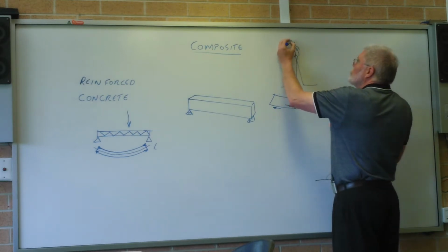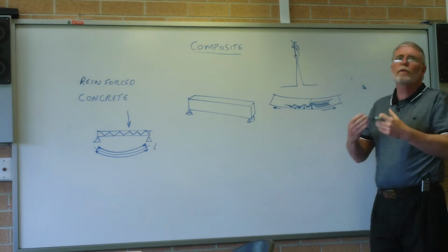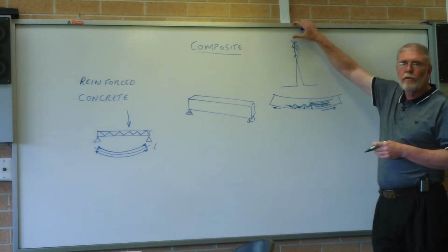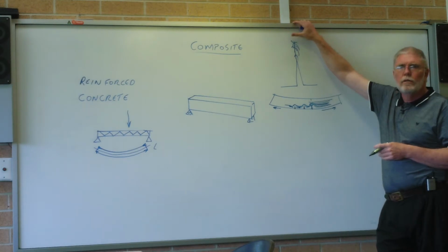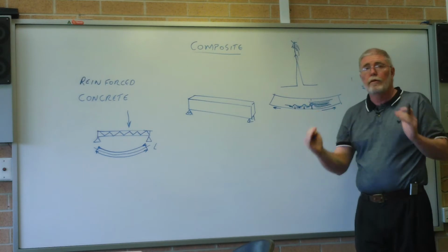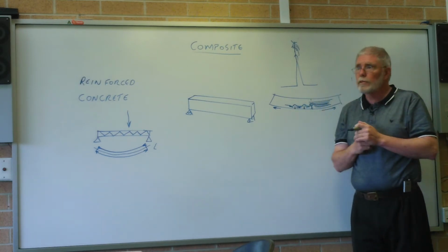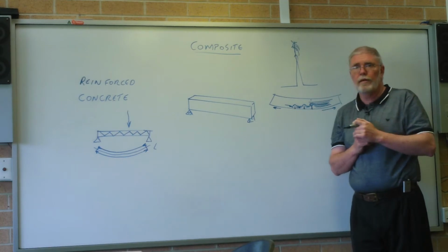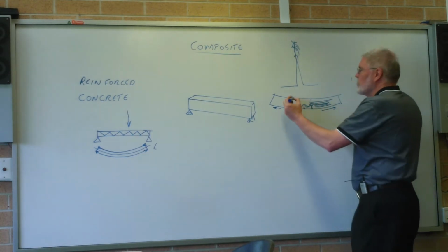So eventually you reach a point where you are overloading the material and what's left in thickness above can't handle the load. It fails. It fails in tension because the cracks open up, forcing the load to the tops of the cracks and making a crack concentrator. What about the cracks on the top?